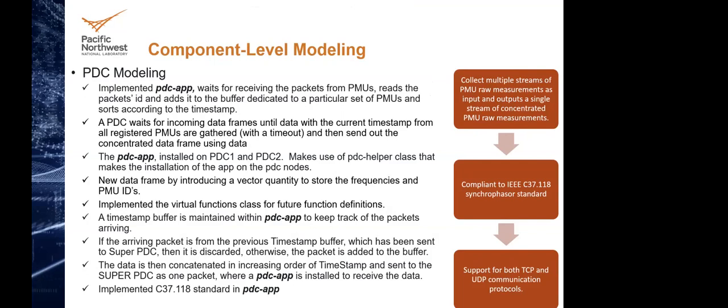Sorry for that. So, the PDC modeling. In this, we are trying to capture most of the features of the PDC, the phasor data concentrator. It has to collect multiple streams of PMU raw measurements as input and output a single stream of concentrated PMU measurements, comply with IEEE C37.118, the synchrophasor standard, and then send it to the historian, or to the application layer, using TCP or UDP.